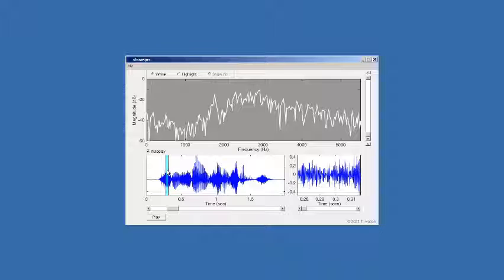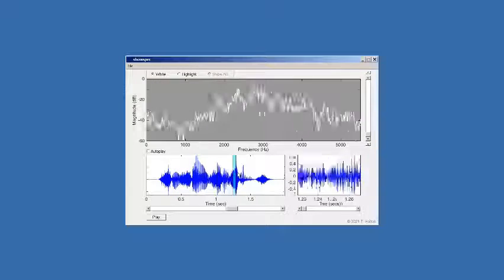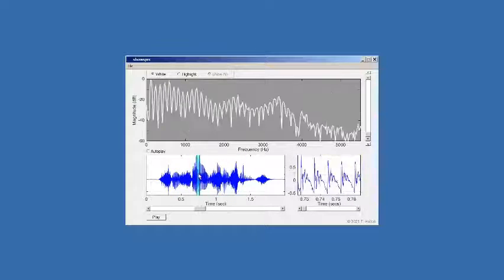The spectrum of this consonant doesn't have a lot of structure. It has a broad peak about 3 kilohertz and very little energy below a kilohertz. You can now show that the spectrum of each little time slice changes from moment to moment. And ask the question, how do we come up with a simple pictorial representation that displays the magnitude of the spectrum as a function of both frequency and time?